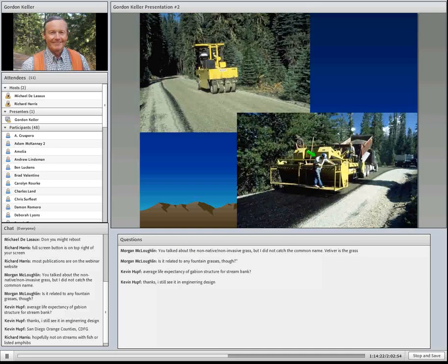What is used a great deal today are seal coats, chip seals. Most of our collector road system in the Forest Service are chip seals. The arterials may go to pavement, but the collectors are often a chip seal. And what it is, it's an application of oil. First you have to have a firm base. And then you put an application of oil down, then an application of chips. We often do what's called a double chip seal. You put a second application of oil, a second application of smaller chips, and then you come back and roll it all and get a nice tight surface.